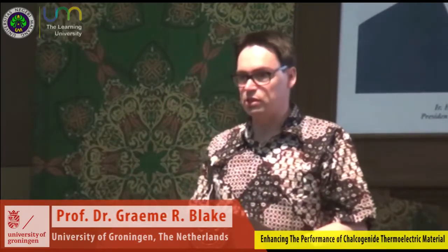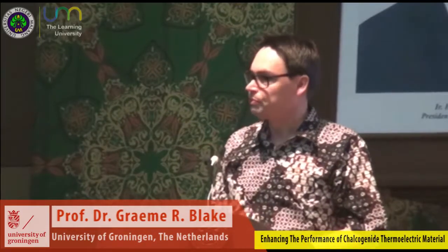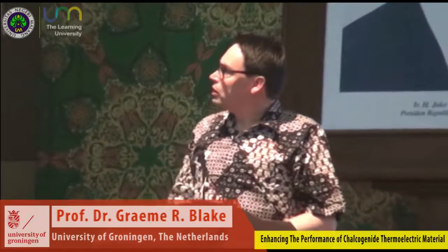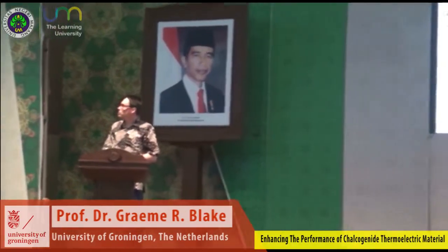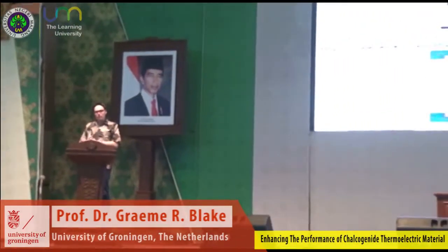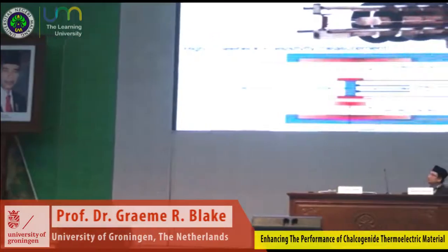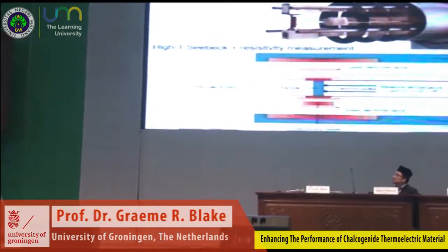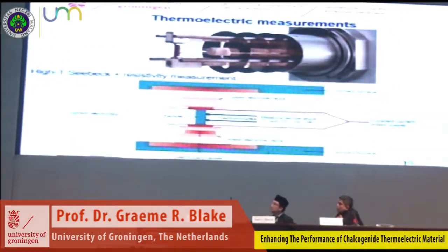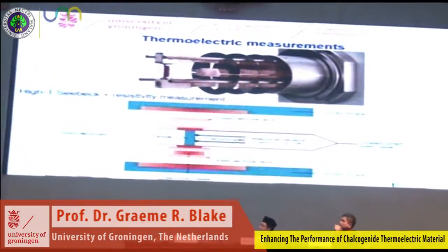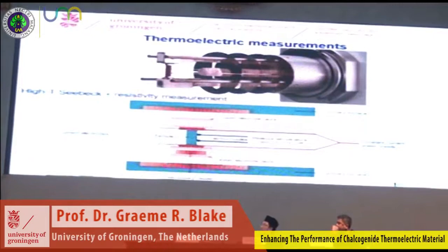So before I go further, I'd like to say a couple of words about how we measure these thermoelectric properties in the lab. I'm an experimentalist, so this is of great importance to us, how we do it. Shown here is the equipment that we use for high temperature Seebeck coefficient and electrical resistivity measurements. We have a sample of a few millimeters in size usually, and we contact the sample along one side with a pair of thermocouples. These also serve as voltage probes when we do a 4-probe electrical resistivity determination.